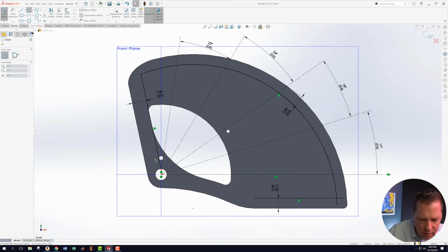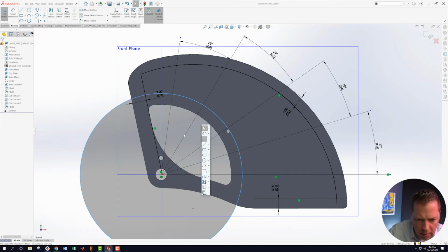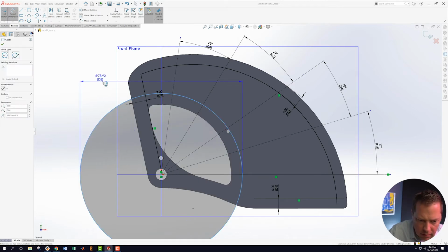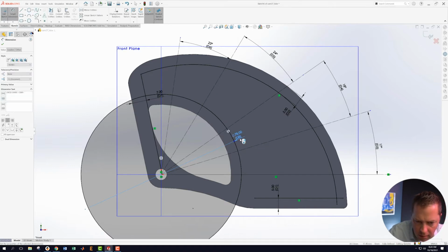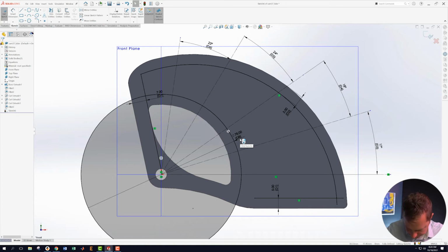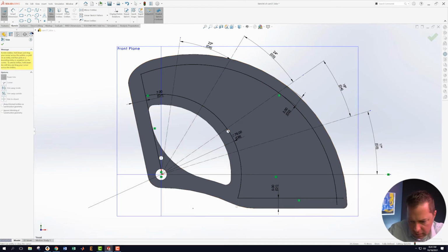Okay, then we have a circle that's 39 from here. Okay. Wow, there's a lot going on in here. So this is sort of just a matter of can I manage everything. This one should be radius 39, so 39 times 2 for the diameter. Okay, great. And it looks like this one, extend entity, is going to extend out to that. Okay, let's trim off some of this stuff we don't need. We don't need this. We don't need those. Ultimately, it doesn't look like we'll need that.